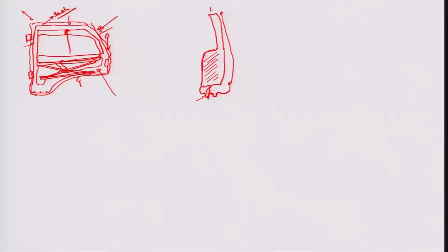So because there are certain holes in the whole periphery of the door which make the fitment of this rubber strip possible, there is always a problem that if some of these holes are, because of the natural degradation of the rubber and the rubber coming off, exposed to splashes, and particularly when the automotive is moving on a road, there is a chance of leakage of water from this gap which is created in the rubber strip.